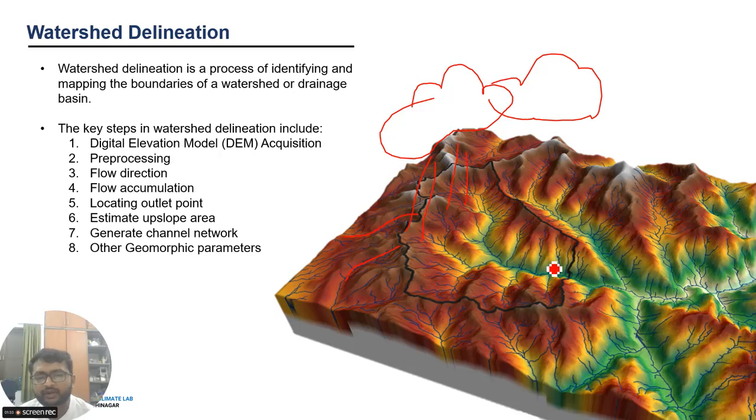Once we get the overall rainfall over the area, we multiply it with the catchment area. Then we get, on average, how much flow it can generate. So let's say this area receives 100 mm or 1000 mm rainfall every year on average, and the area is 1 square kilometer or 10 square kilometers. We convert the area and the rainfall into meters, so everything becomes cubic meters.